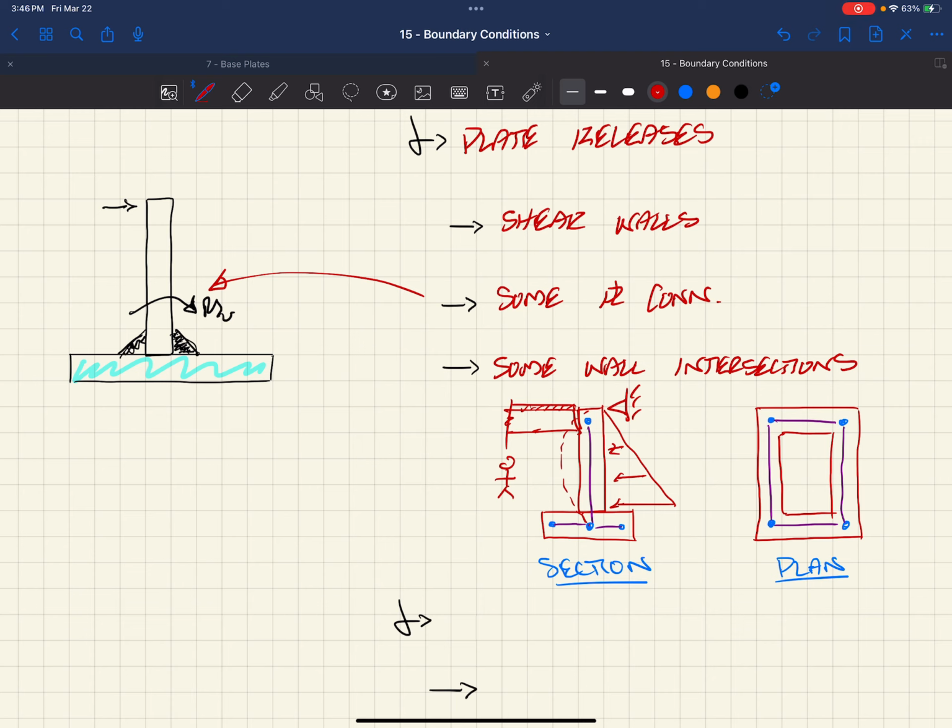So now you could have it as a fixed pin if you really wanted to, or a pin, right? I usually go with pin, and if that's the case, now all of a sudden your rebar obviously needs to stick to one side of our wall instead of originally being on the loaded face. Right? If this was a fixed wall, we'd want the reinforcement on the tension side of our wall, which would be on the loaded side.